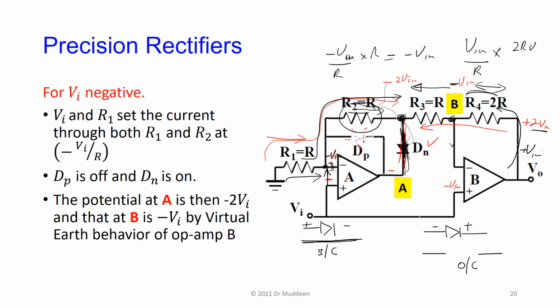As I mentioned in classes, like a valve, it's either on or it's off. The op-amp makes sure that the diode is biased fully on or totally reverse biased. So you're safe to assume, when this one is off, that we have absolutely no connection in the feedback loop here, so you could even redraw the circuit as though it didn't have a diode in it.